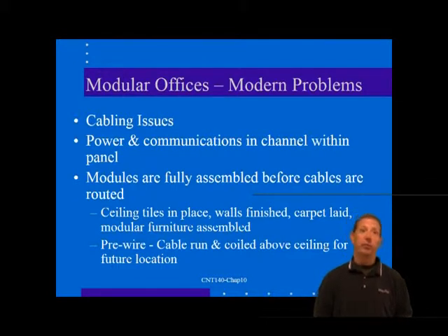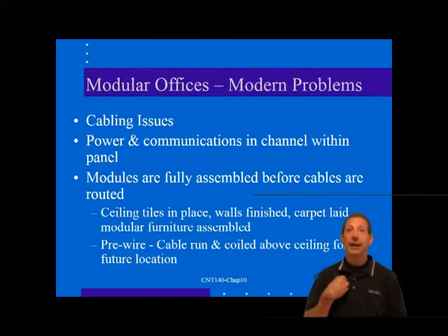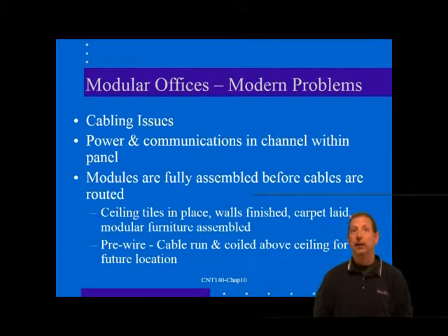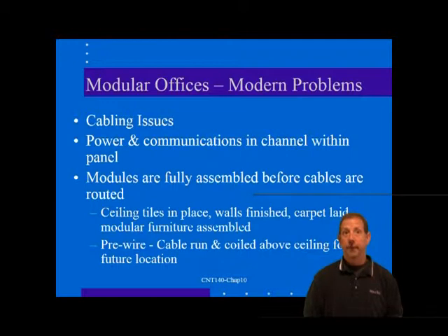In some instances, the distribution point might be in a ceiling area with the communications wire distributed to the furniture modules nearby. Then, after the furniture is installed, cables can be extended from the distribution point to the workstation outlet within the modules. This has now become an almost universal practice in open office installations. This method is not only much more practical, but also a good deal less expensive, labor-wise, than dealing with home runs.